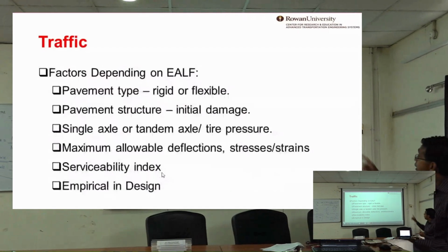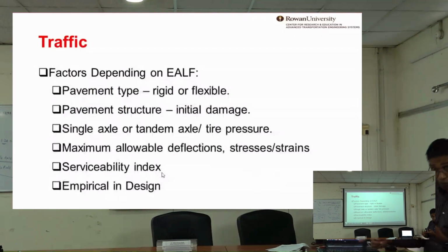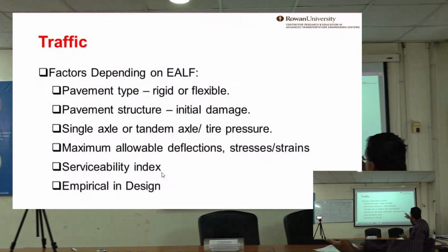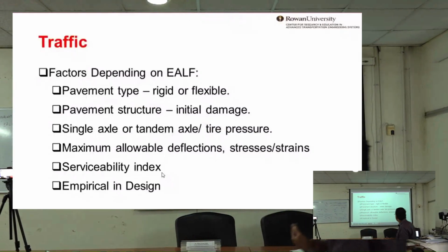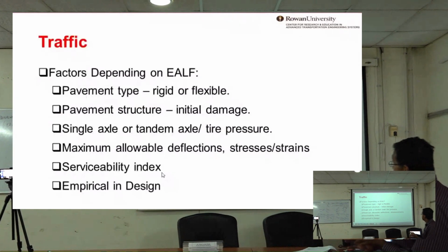The ELF depends on the type of pavement, rigid or flexible, I just explained that. It depends on the initial damage, a brand new pavement or old pavement. It depends on whether it's a single axle, tandem axle, or tire pressure.